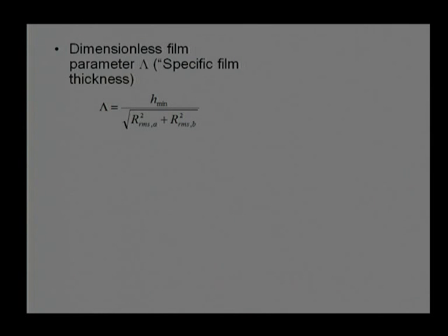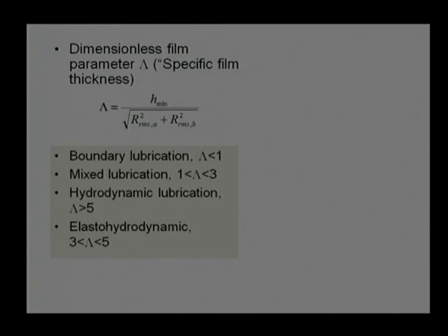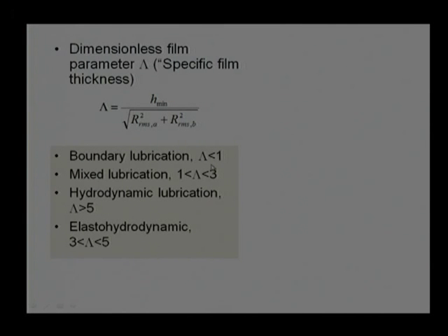If the capital lambda value is higher, then the operating mechanism will be different and the overall result may be in favor of the surface. So, we generally divide the complete lubrication mechanism into 4 domains. We say that the lubricant is negligible. That means there is hardly any film thickness between two surfaces. In that case, capital lambda will be lesser than 1. That means surface roughness is a higher value compared to film thickness.